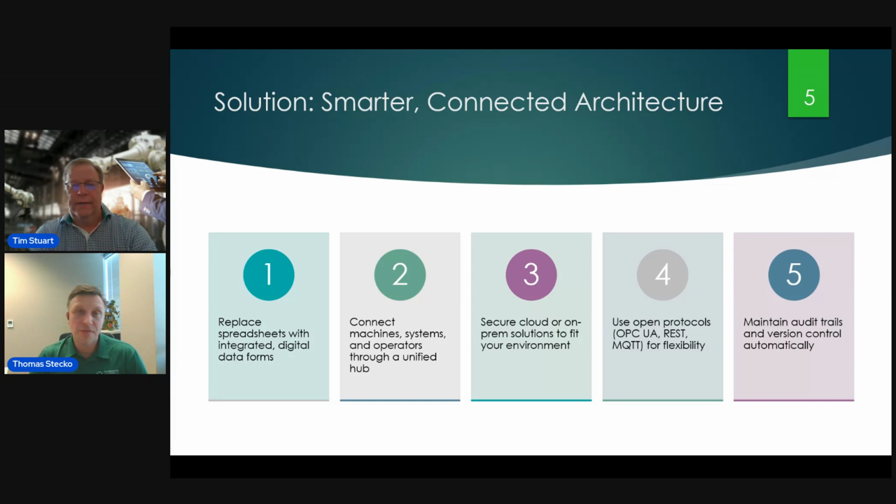And really, another thing is getting that specific data. Right? Do we have machines that have LAN cards? Are the machines networked? If they're not networked, is there a technology out there that can let us gain access to those tags? And then we have to think about how do we move that data, using Ignition or ThingWorx or Tulip, like I mentioned in the past. We can utilize OPC UA servers, some sort of an MQTT pub/sub protocol to get the data in there.